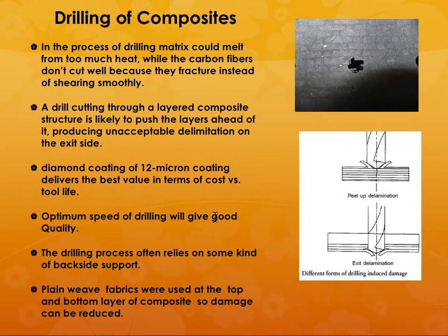So first of all, you have to have diamond coated tips, or titanium nitride coated tips, and you have to have an optimum speed of drilling so that it will give you good quality, and you don't want the fibers to break and create weak joints here.